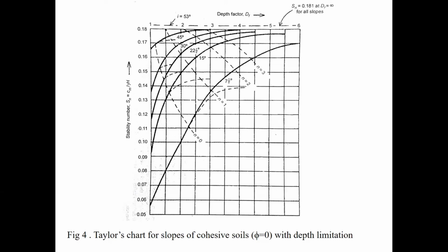Factor of safety with respect to cohesion is given as 1.5. Now you have to find out, for a factor of safety of 1.5, how much cohesion should be mobilized, isn't it? So now you have to back calculate your Cm. How much is your Cm? 18, correct. So for a Cm of 18, how much will be your Sn?